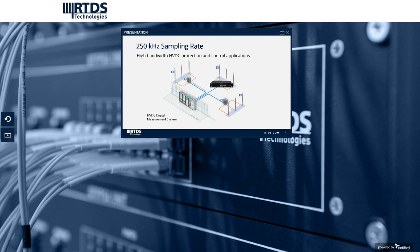The figure here shows a vendor's HVDC digital measurement system. From the switchyard here, it can generate SV using this high-speed merging unit. SV will feed back to the protective devices in this cubicle here. Similarly, using the GTFPGA-SV, it can also generate 250 kHz SV and send it back to the protective relays inside those cabinets. And one GTFPGA-SV can replace 8 merging units in this scenario.